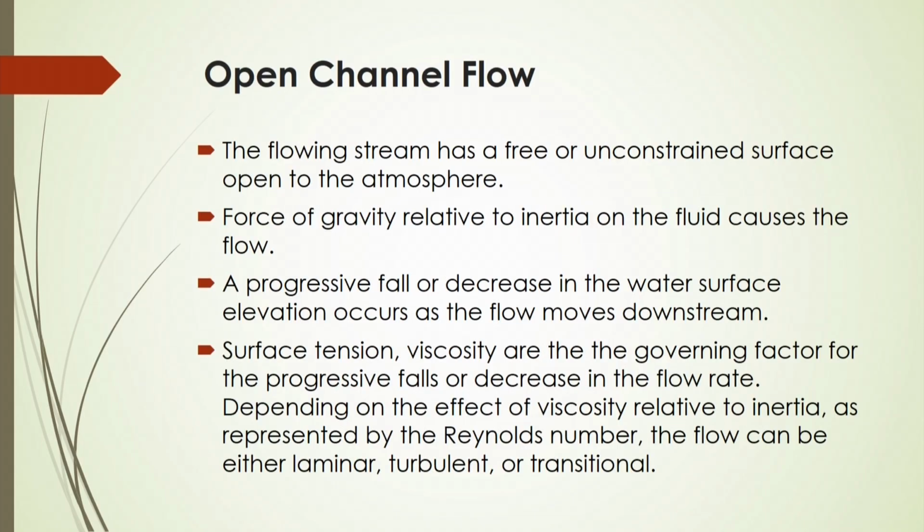Now, what is open channel flow? In this case, the flowing stream has a free or unconstrained surface open to the atmosphere, and the force of gravity relative to the inertia, which we have already discussed, causes the flow. A progressive fall or decrease in the water surface elevation occurs, and as a result the flow moves downstream. Surface tension and viscosity of the fluid will be the governing factors for the progressive decrease in the flow rate in the channel.